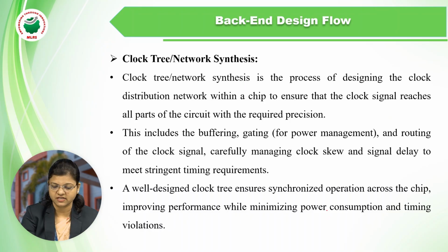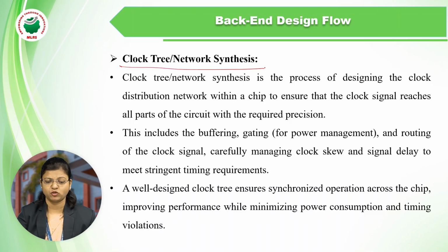Then comes the clock tree synthesis. In clock tree synthesis, we are mainly focusing on the timing and clock, whether we are providing the clock to each of the blocks or not.